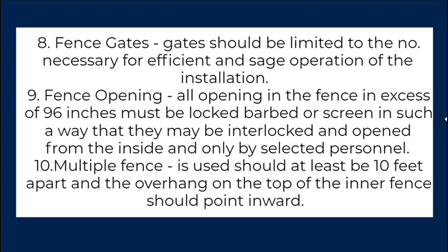9. Fence opening. All openings in the fence in excess of 96 inches must be locked, barred, or screened in such a way that they may be interlocked and opened from the inside and only by selected personnel. 10. If multiple fences are used, they should be at least 10 feet apart and the overhang on the top of the inner fence should point inward.